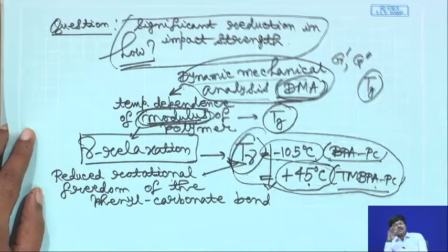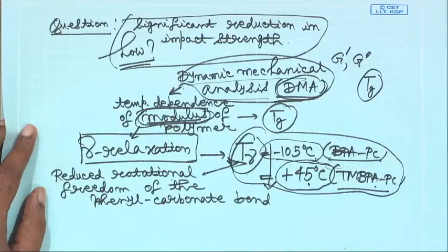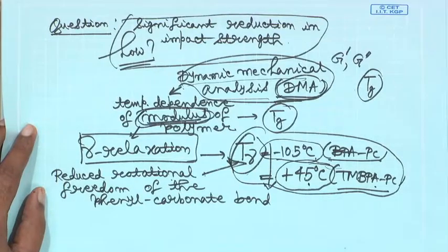Somewhat intuitively you can understand that when you are giving an impact to the material, it has to absorb some energy, and yet it has to distribute that absorbed energy in the material. This possibly happens because you put some energy and there might be slight rotation here or slight rotation there of the bond, and it can absorb some energy, and if you stop that you cannot absorb and distribute this energy. So, it is an intuitive way to understand to correlate the relaxation.